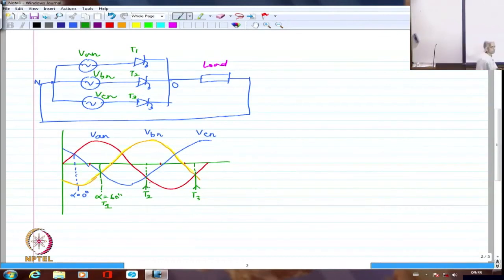And in this case, that's why in three-phase converter, we will not give a firing pulse whose width is 180, rather we will give only 120, because we would not like to give the firing pulses to two devices simultaneously. We would generally like to give only one device at a time, and T1 will be given for 120 degrees, T2 will be given for 120 degrees, T3 will be given for 120 degrees with high frequency ANDing and pulse transformer, pulse amplification, everything. The same kind of circuit will be adopted. Pulse width is 120 degrees. That's all is the difference.